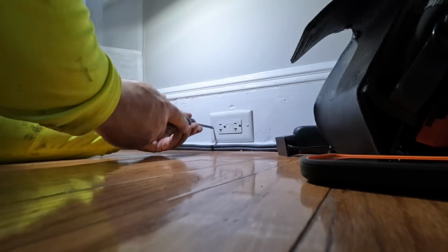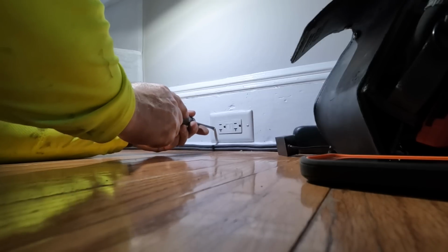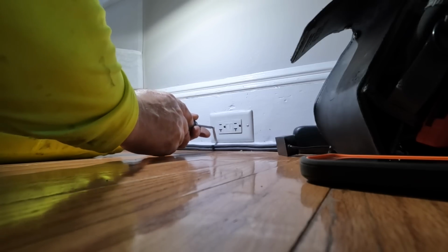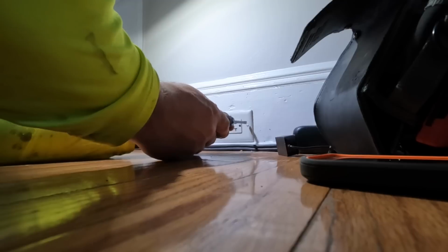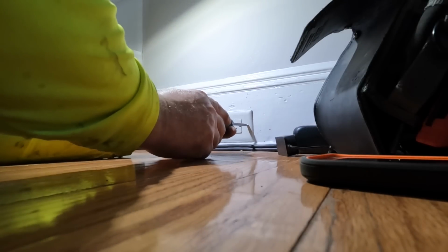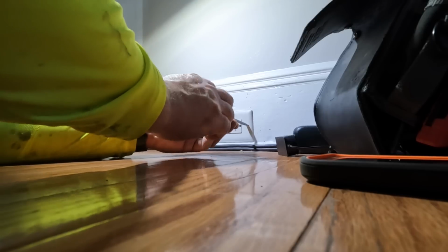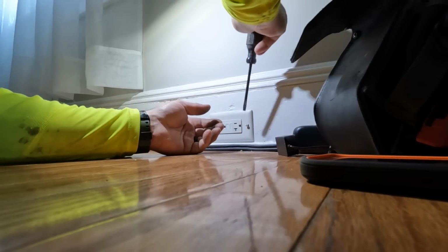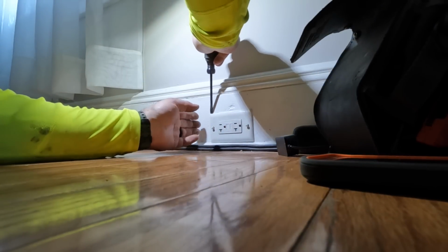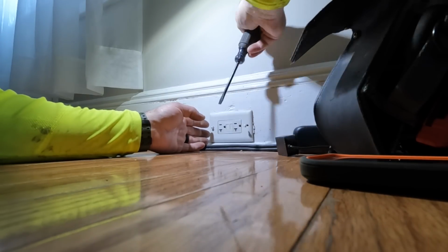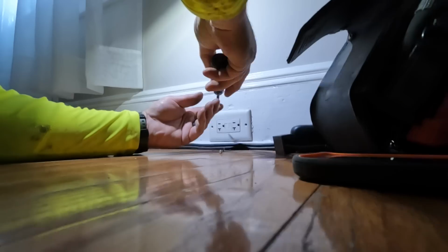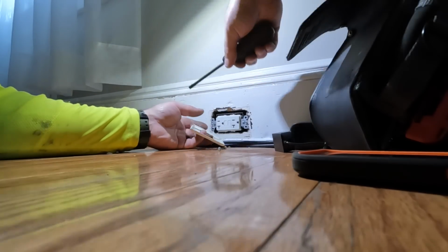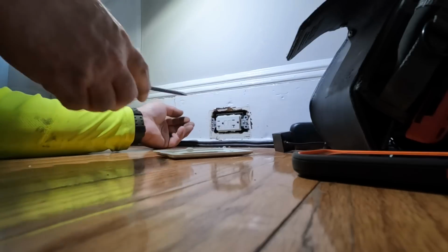Okay, so as you can see, this one was also GFCI protected with no equipment grounding conductor present, and I'm about to find out that there's actually an old piece of Romex that's up into this outlet box, except they just wrapped the equipment grounding conductor around the cable itself and never attached it to the box, which makes no sense to me. So I was halfway through this already, so we got rid of that.